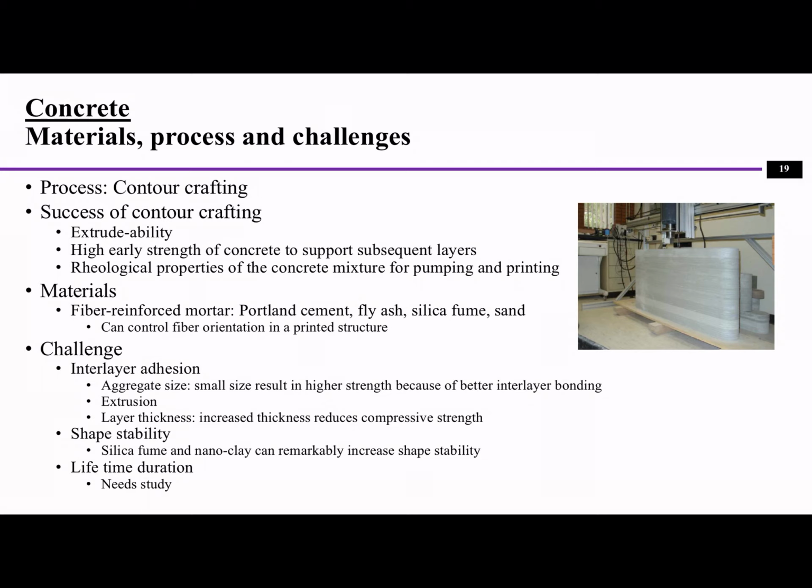If the viscosity is really high, it will cause some deposition problems. Also, when we are printing concrete materials, we create different layers, and a high early strength of the concrete can support subsequent layers on top of it.